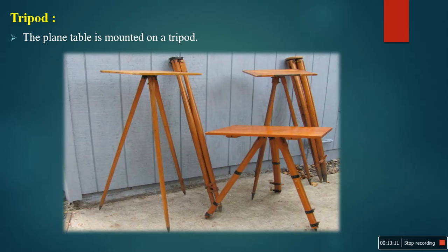So we can easily move horizontally, radially or longitudinally. Likewise, you can attach these legs like this. Then you can easily remove this in open spaces, and you have to attach your plane table on the top of the tripod legs.